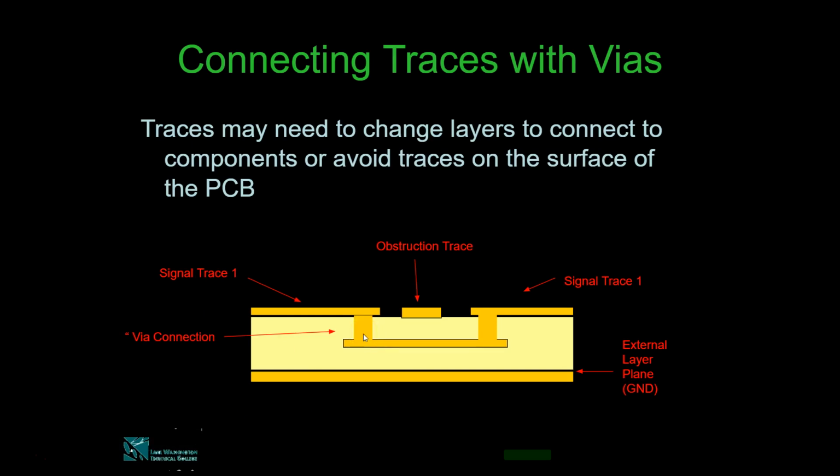The most common variable in trace design is the width, but the trade-off is an increase in capacitance. Sometimes the physical dimension of the trace becomes very critical, such as when routing digital signals. The length may need to be kept the same to reduce the timing error, or for high frequency like radio frequency signals, the trace may need to be impedance matched to the source.